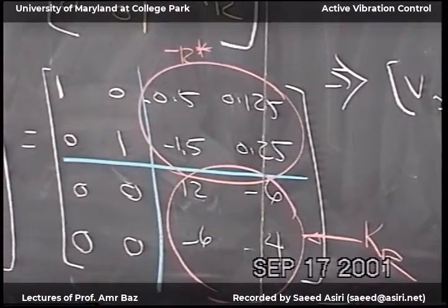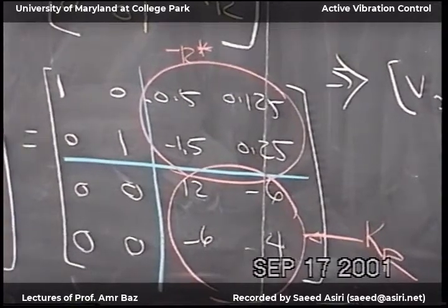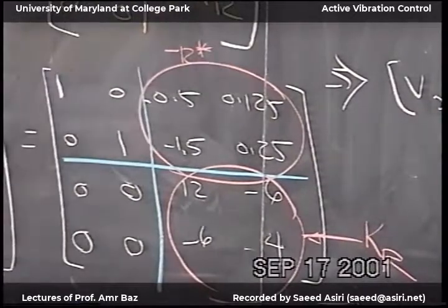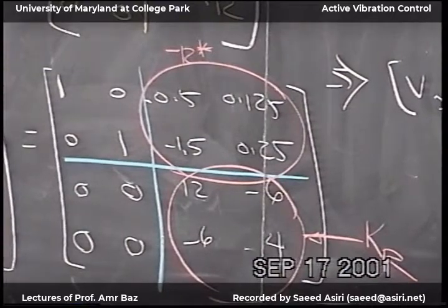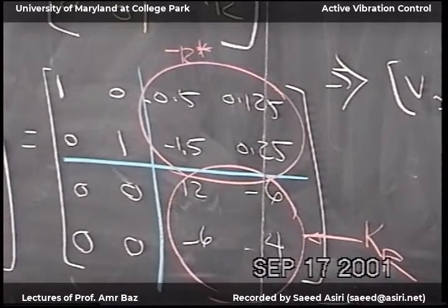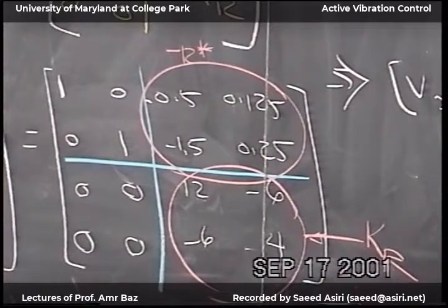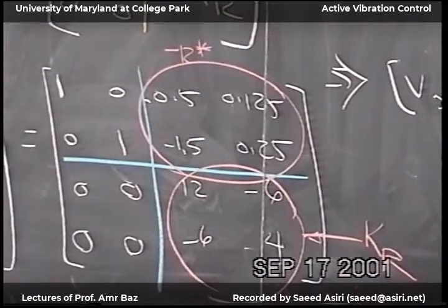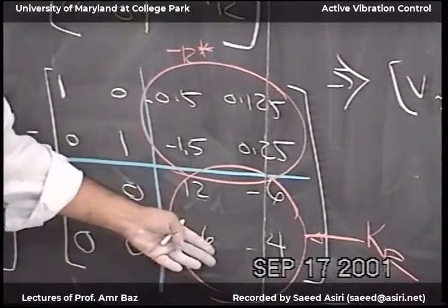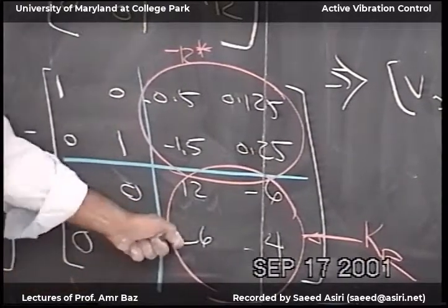If I take the original system matrix and throw away the rows corresponding to delta S and the columns corresponding to delta S, the result is here. Has nothing to do with this. We did not throw away columns and rows. We used the connectivity and maintained it. Maintain the relationship between delta S and delta P and modify this matrix accordingly. So now this is my reduced order matrix.